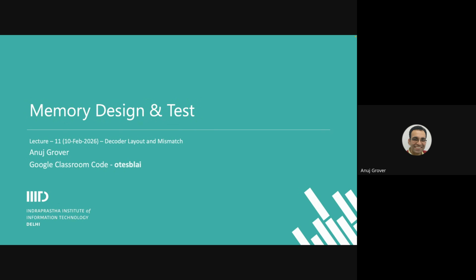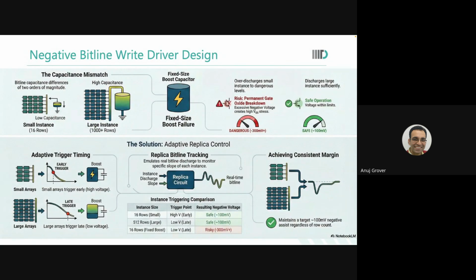And in that, we identified that there are 5 stages of operation of a sense amplifier. And then we had moved to the write driver. And we saw that there was just some very basic circuit of write driver that we had thought of when we talked of the 14 transistor D-latch conversion to a 6T memory cell. At that point of time, we said we will put one NMOS in the bottom, and that is our write driver.